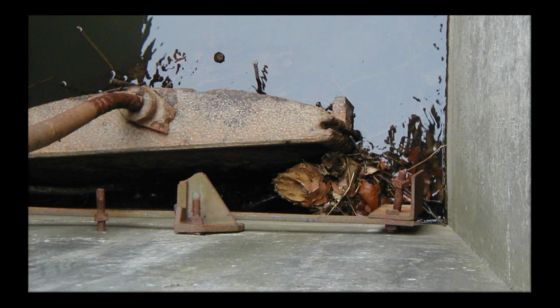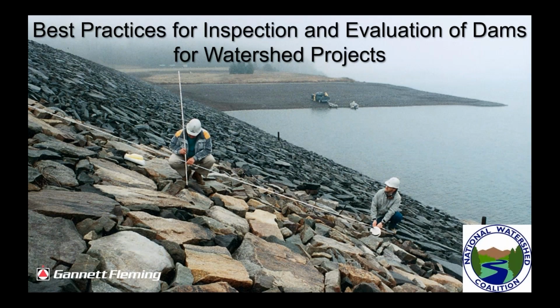So the rule is maintain those gates per manufacturer's instructions. They need to be lubricated, they need to be exercised, and never apply more force than one person, like a 40-pound force, to operate the gates. So Ray, that's the content for this 90-minute presentation, and I would welcome any questions.